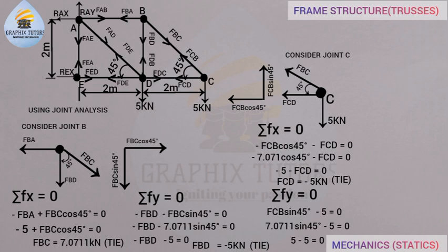So I calculated for 4 joints. Now the reason is this: if I say I want to calculate for joint D, the value I'll be getting will be 0, 0, and 0. And again, I'll be getting back the same answer I've gotten before. So there'll be repetition. To avoid repetition, you only calculate for 4 joints if you have 5 joints, or you calculate for 3 joints if you have 4 joints, right? Which is what I just did here. So that's what we have.